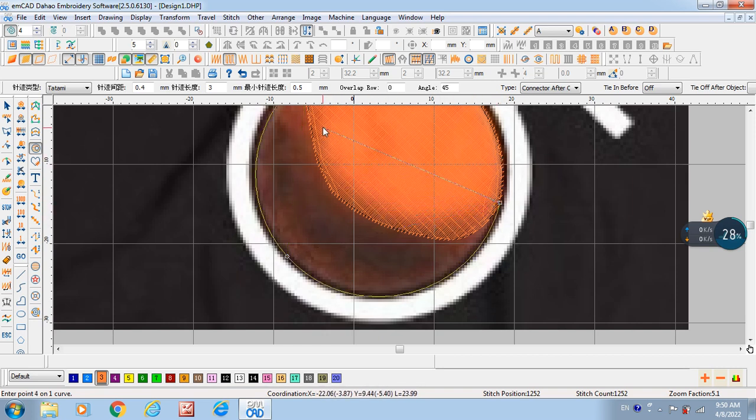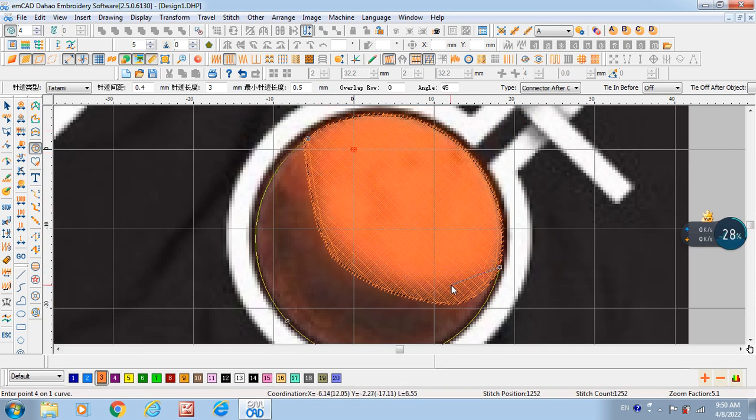Then I need to follow this area, see, so this line here looks like is different color, still maybe here, so I go more, then I can do down is right click, and finally have to finish with left click, and left click, then to finish this one I do enter on my keyboard. So now enter means I finish the shape, then I need to decide where to start.